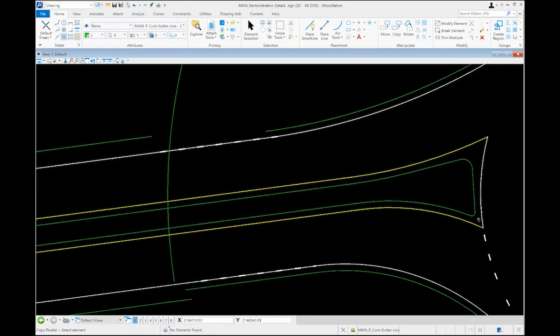In addition to the 20 feet of storage, we're going to end up with a 10-foot wide pedestrian crossing. So if I'm working to the middle of that pedestrian crossing, I'm going to have 25 total feet to the edge here, plus another 2 feet for that offset. So that's a total of 27 feet. So I'm going to set a circle as a guide that's got a 27-foot radius.